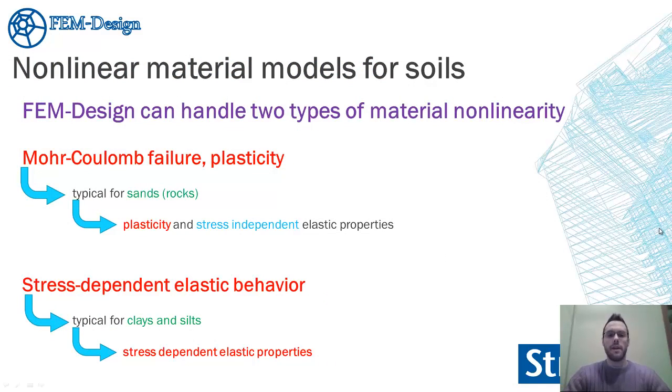So FEM-Design can handle two types of nonlinearity. The first nonlinear material model is the Mohr Coulomb failure and the Mohr Coulomb plasticity. It's typical for sands or maybe rocks, and the plasticity is applied here, and the elastic properties are stress independent.